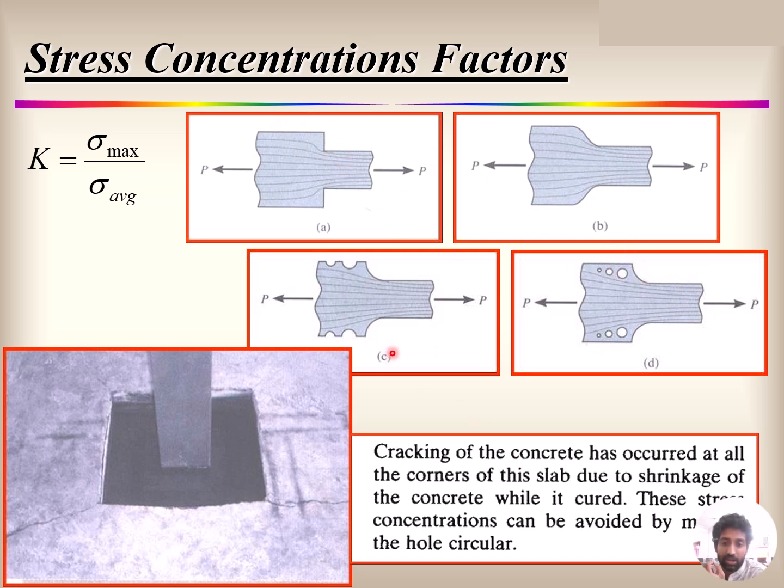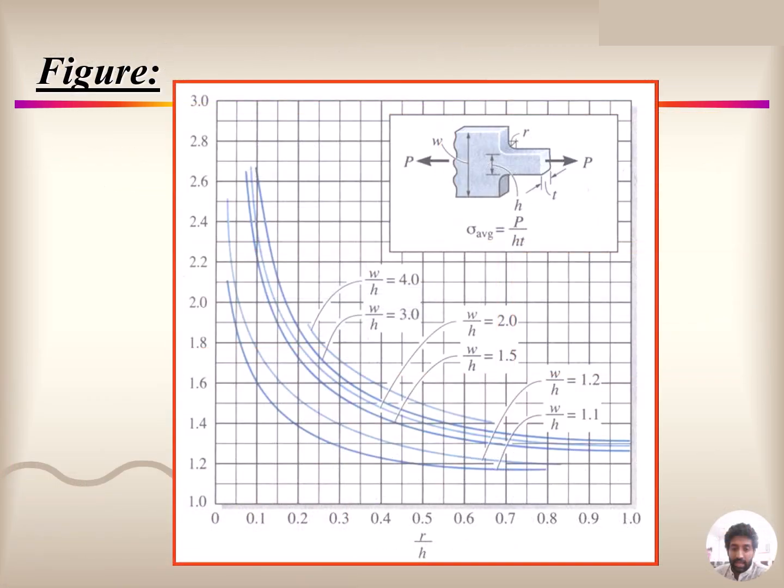After that, we applied some rules. This can be done when there is a step or a sharp corner like this. You need to go for a fillet zone, and you have to do the fillet work. If you do that fillet, the stress will be distributed equally. Next is a pattern where you can find the maximum places.